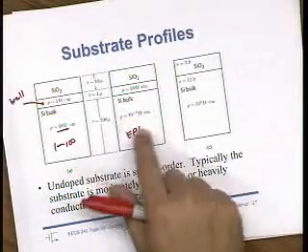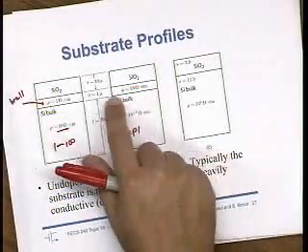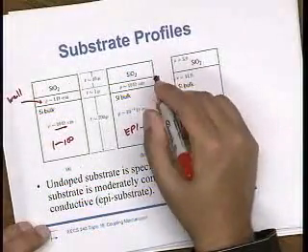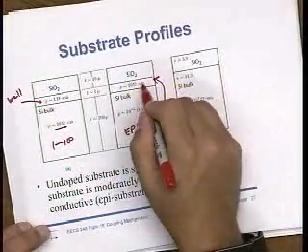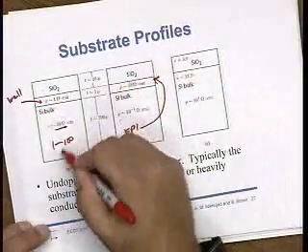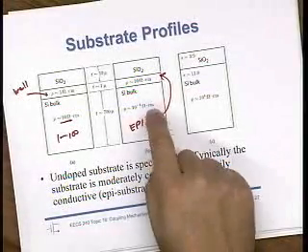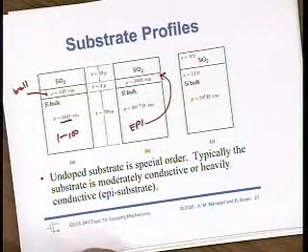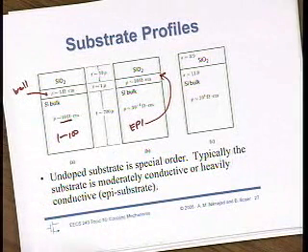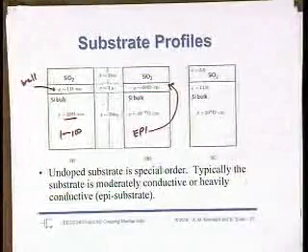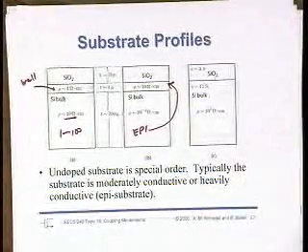And because you can't build transistors in the body, you have to have a layer which is called the epi layer, epitaxially grown, that has the same conductivity of, let's say, the bulk here. And this is where you're going to form your transistors. So why is this good for digital? Why did people even use this if it's more expensive? Any ideas?